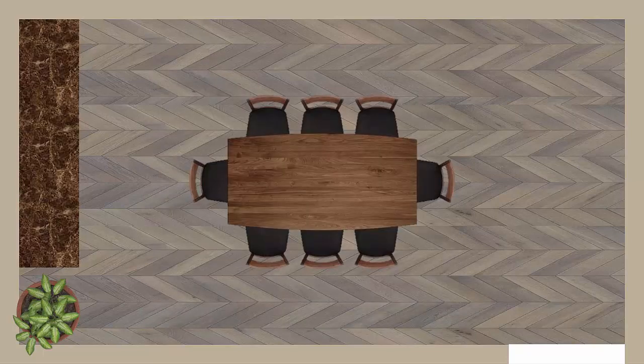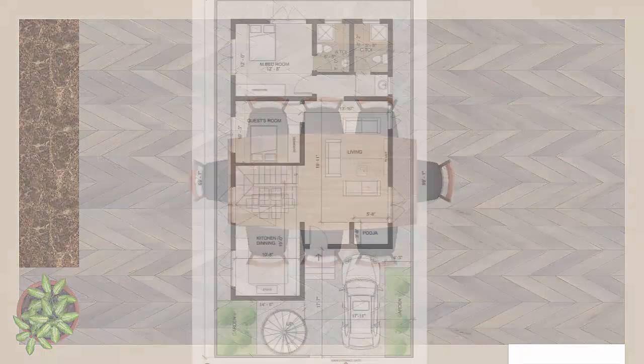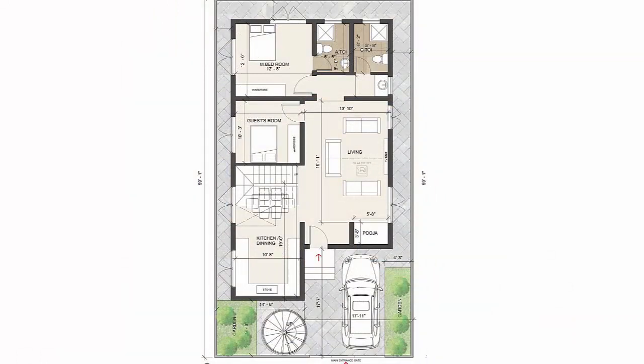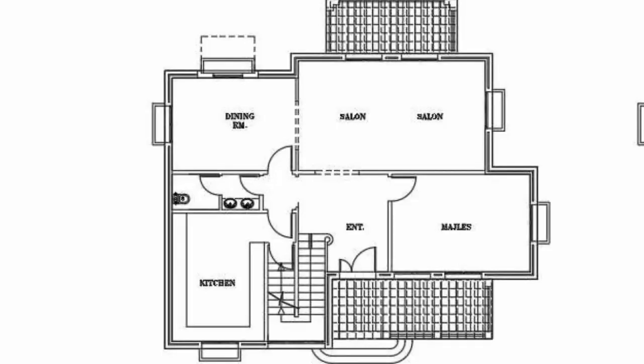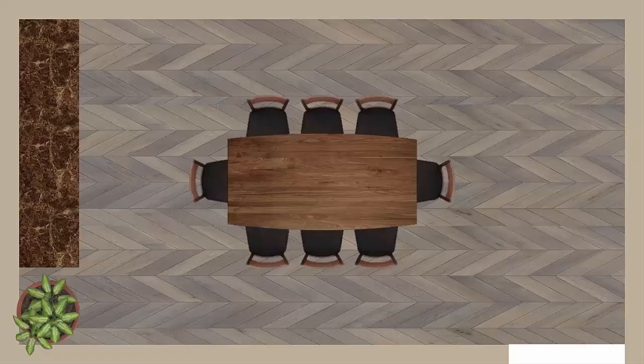Okay, when you're working on any project, even in the AutoCAD plan, you can say this room is dining or this room is bedroom or this room is hall or a kitchen by its furniture, right? Or even if you didn't receive any furniture layout, it will be mentioned there in a text format that this space is a room, it's a bedroom, it's a kitchen, right? Now same way we are going to perform lux calculation and we have to convey this information to Dialux. Look, this is a bedroom, look, this is a living room. So how am I going to say this to Dialux?